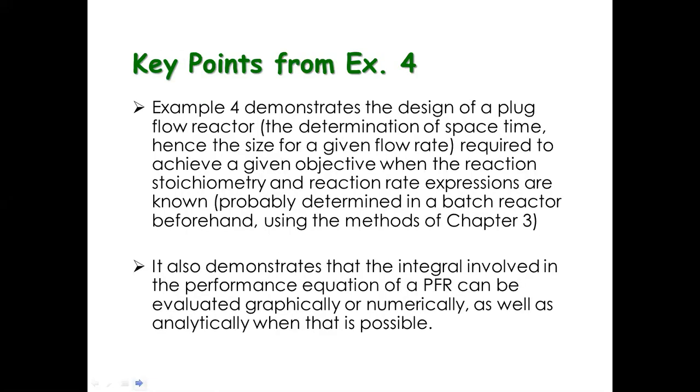So what are the key points that we should be learning out of the exercise of having to determine the space-time for a plug flow reactor? So this example demonstrates the design of a plug flow reactor, the determination of the space-time that is. And if you're already given the space-time, then if we are provided with the flow rate, we will know the size of the reactor.